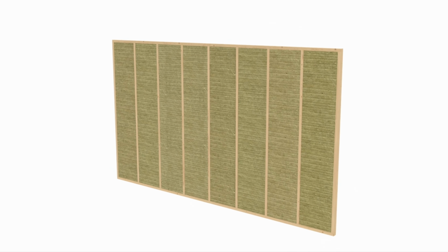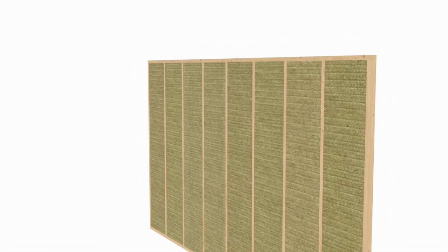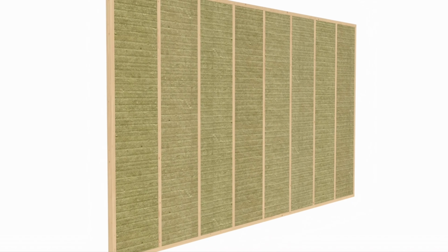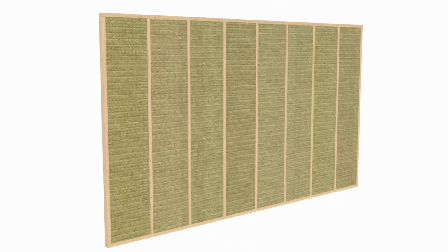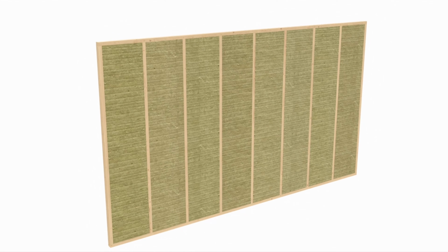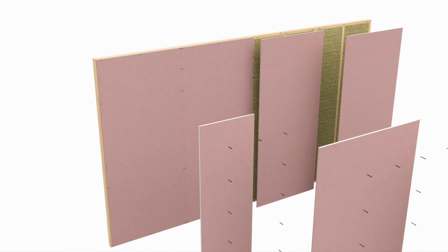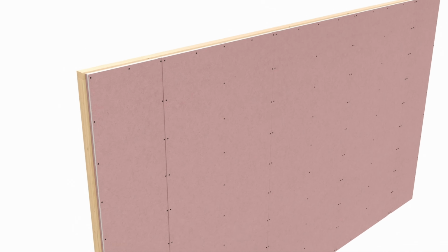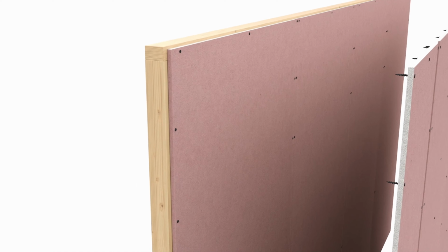The method of fastening the boards to the wall element depends on how many layers of boards will be used. As a rule, there are no more than 3 layers, however, most often they are limited to 1 to 2 layers of boards. The more board layers there are, the less often the step of fasteners, screws, of the lower board layer, since the fastening screws of the upper boards also pass through the lower board layers.